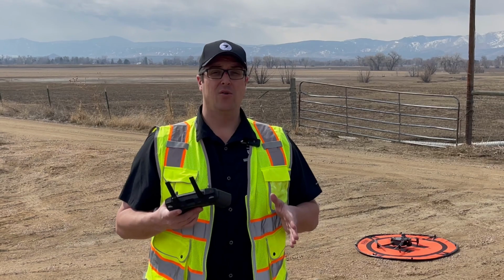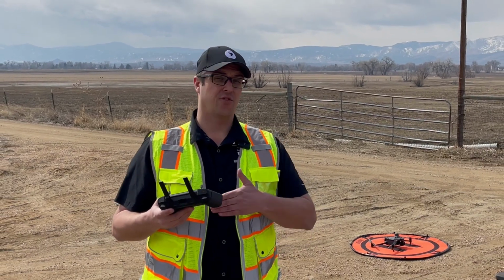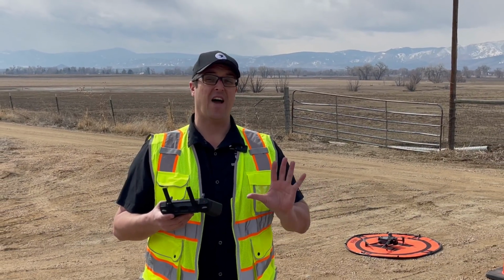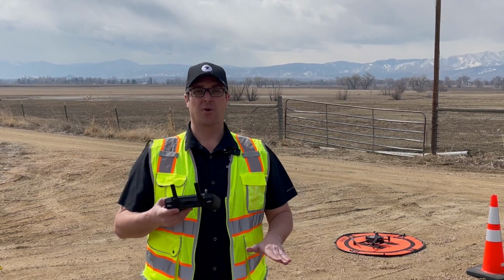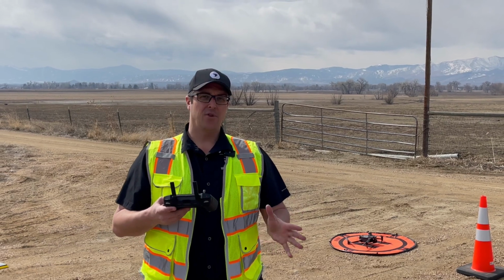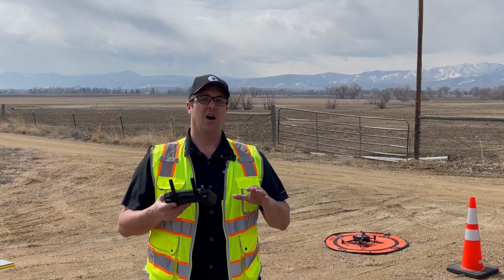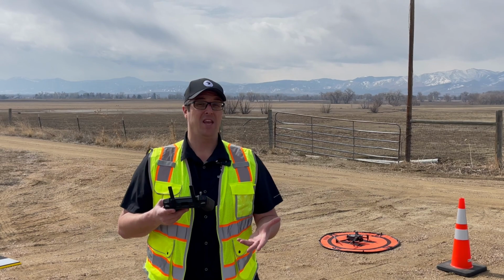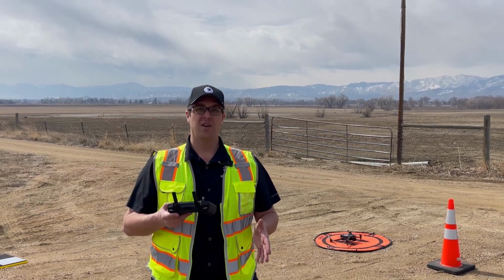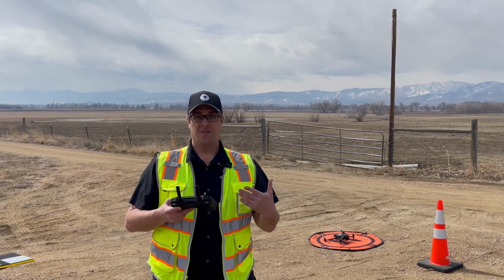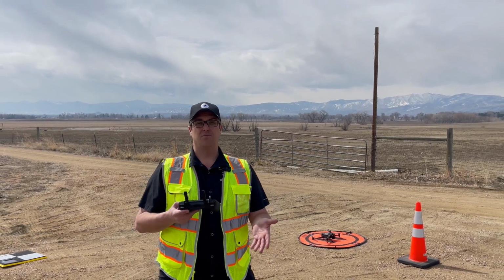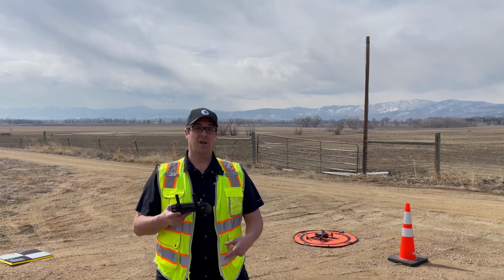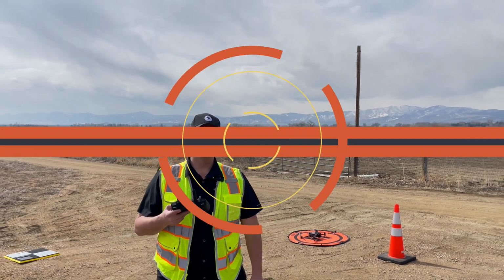All right, so before we shut it down, we're going to let it log the RTK for a little while longer. I let it run for about 5 minutes after landing. You can do this at altitude if you want to hold, or you could do it on the ground as well. Just give it a few minutes after you land. Time is your friend in these types of operations when you're using GPS correction. The longer you have it sit, the better your solution will be. So we're just going to let it sit and then head back into the office, and we'll meet you there.